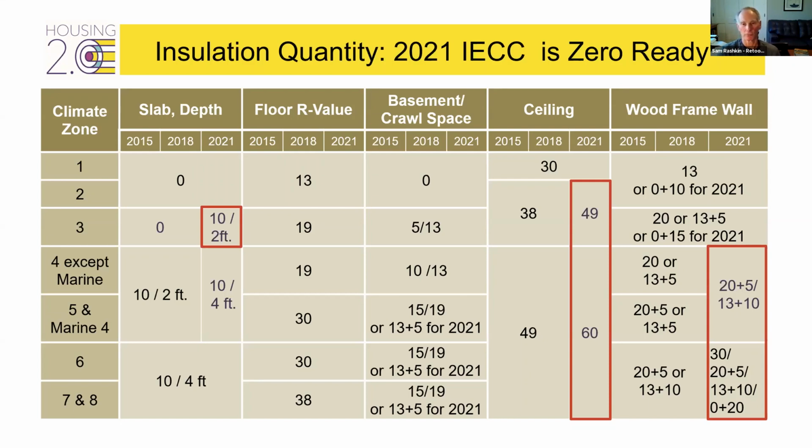It gets to be much more reasonable numbers when you factor in the other things you do inherently with high performance. If you have unvented attic and effectively the benefit of a raised heel truss equivalent, your prescriptive numbers drop to levels that are much more achievable. And that's where you want to be.